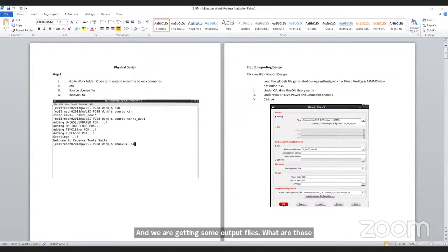Bhuvaneshwari, very good answer. Combined together, core area plus IO area is the die area. Die is the outer part of my chip. From die to IO ring, we are going to do packaging. Packaging is nothing but the black color part of my chip connected with the silver pins, which we see in our lab in any 555 timer or op-amp 741.